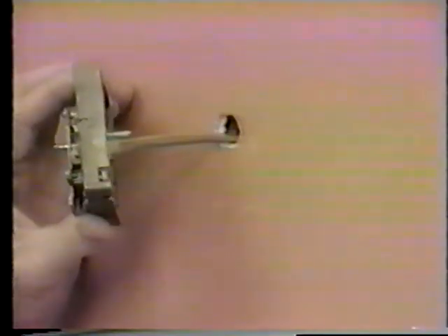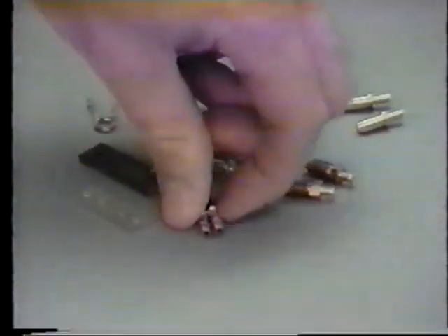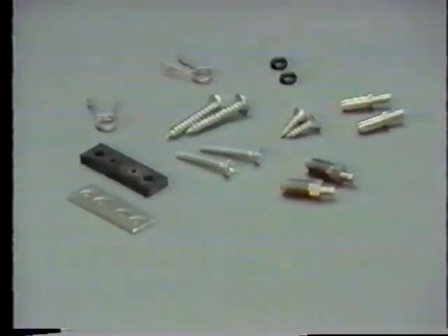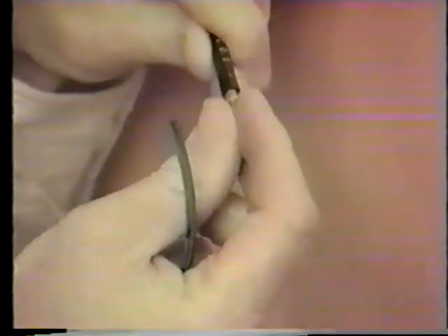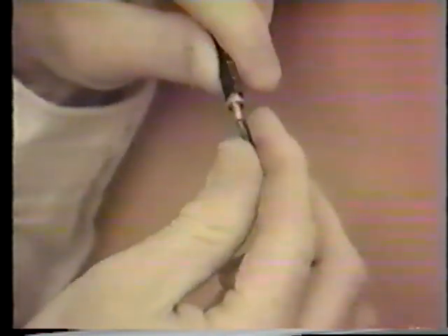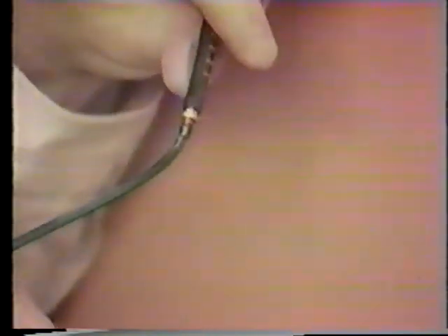First, read over the data sheet, selecting the information that best suits your conversion application. Next, remove the old thermostat and any bracket from the wall. Determine the appropriate fittings for connecting to the pipe head. If the fittings in the kit will not directly attach to the pipe head, then it will be necessary to cut off the old pipe head and connect directly to the tubing. Connect the 3/16" OD Tygothane tubing to the pipe head adapters or directly to the tubing.